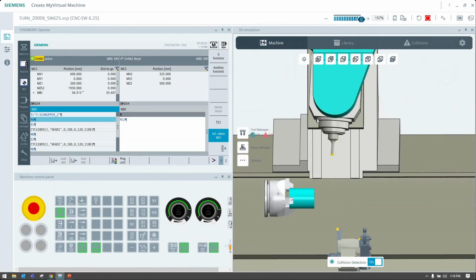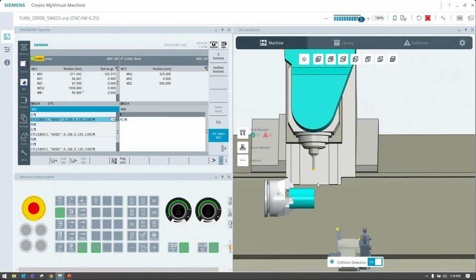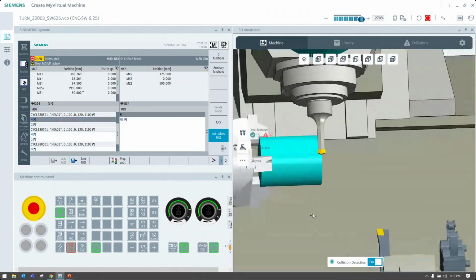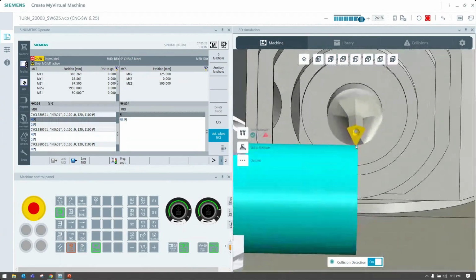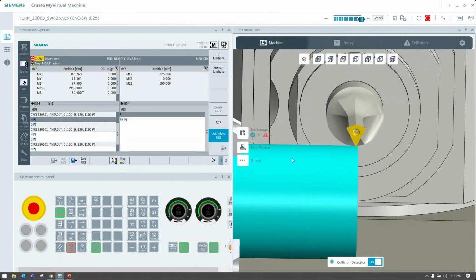And we have cycles prepared for this, but as we can see, we're positioned on the Y-axis, right? And we're in the 0 position. We're controlling this with edge numbers. So this is D1, right? But in D1, I can change this angle and use whatever side of the insert that I want.